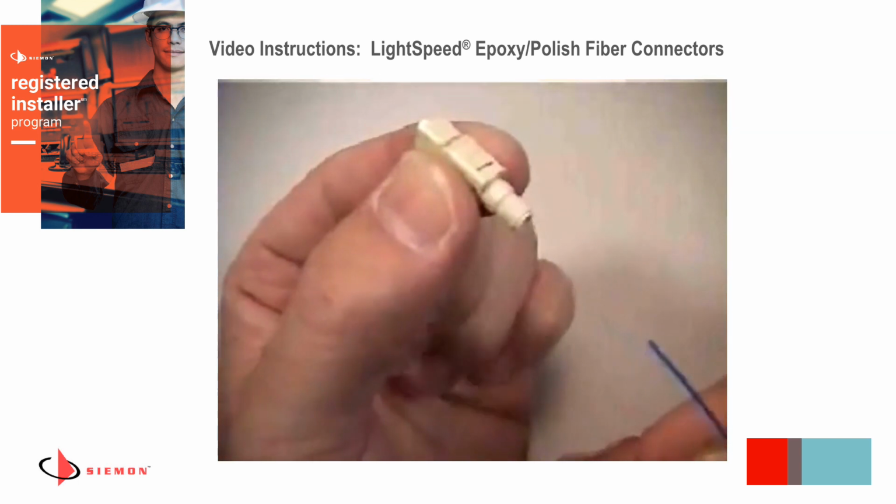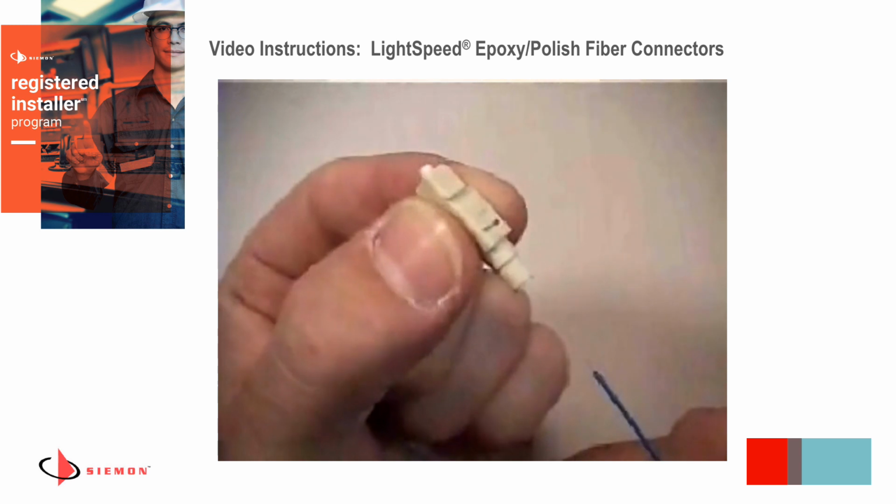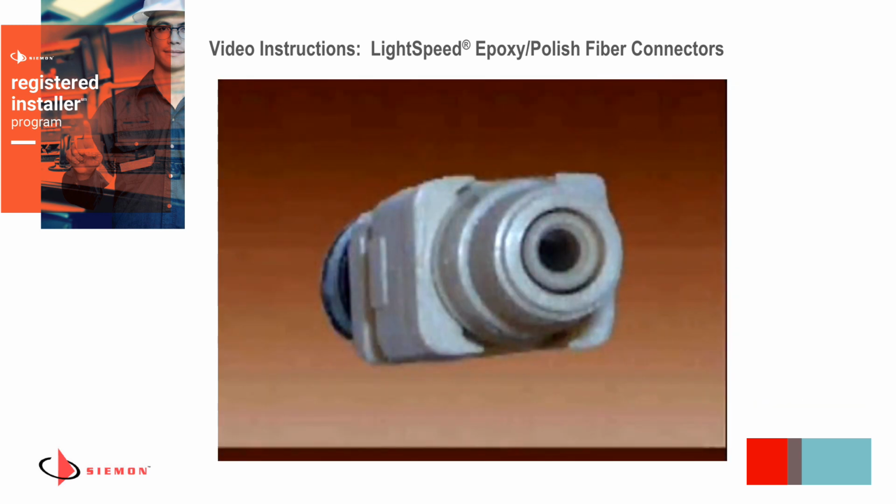Next, insert the fiber into the connector until the buffer bottoms out inside the housing. Be sure the fiber is being inserted into the center of the connector and not the space between the inner and outer body. If the fiber seems to be catching within the inner body, it may help to rotate the connector during insertion to assist in guiding the fiber into the ferrule.